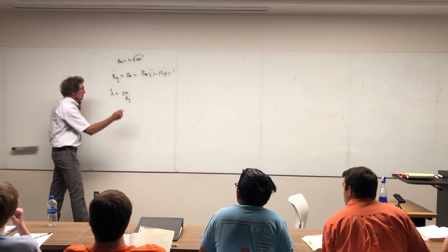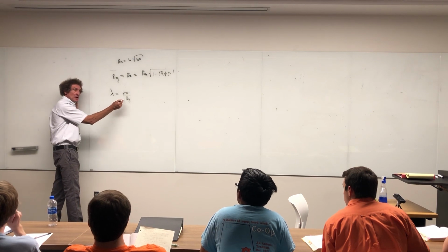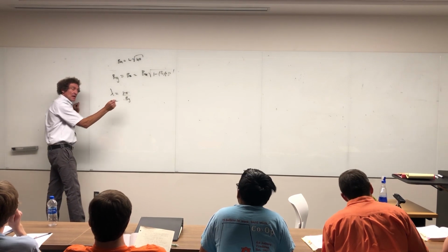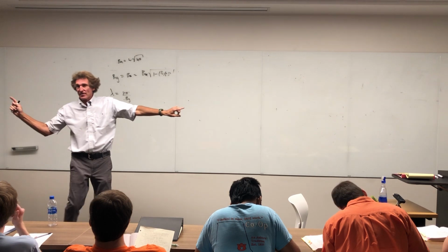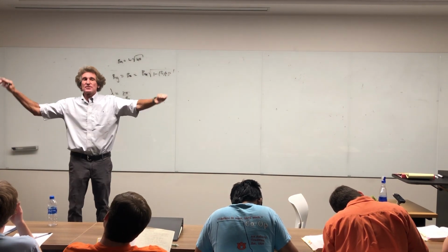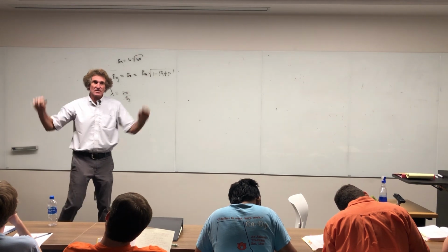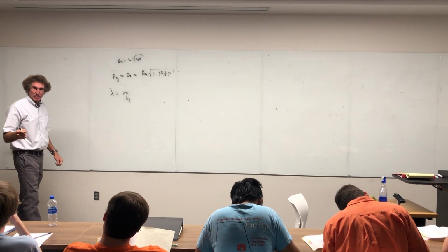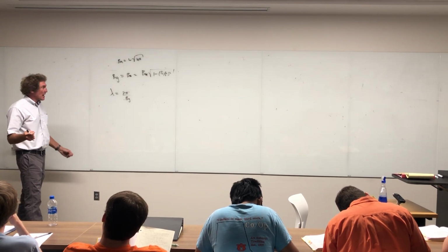Now, if it becomes 0, what does the wavelength become? Infinite, right? That means basically if you've got an infinite wavelength, it means there's no variation. And energy at cutoff is just bouncing top plate, bottom plate, top plate. It's like a resonant cavity at that point. With me?